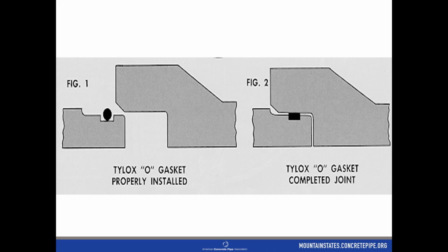When you stretch that rubber band over your hand, it's going to pull to one side. So it's going to be really tight, with less material on one side than on the other. When you run your finger around the outside, it balances the amount of rubber material around your wrist. It's no different in these pipes. As you put a rubber gasket on, you tend to pull it from the top down to the bottom, so it's a little tighter at the top and has less material there than at the bottom. By equalizing, you're moving that rubber material around the entire pipe so it's more balanced, and you don't have more material in one spot that can crack or break your bell in the joint. So make sure we're equalizing those as we put them in.